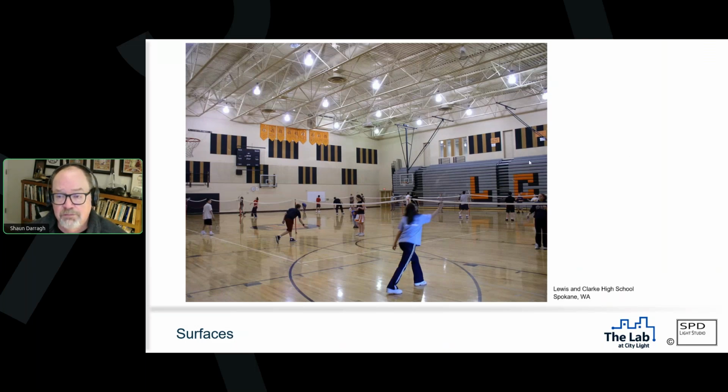where they came and they said, well, we need better lighting. We need more lighting because it's too dark in here. The reality was, if you took a light meter onto the floor, they had abundant light. But from a perception standpoint, the walls and the ceiling are painted. It's a little bit hard to tell, but you can see this fellow's t-shirt is white. This is a dark cream color. They chose intentionally to paint the walls and the ceilings this dark cream color because those are the dominant surfaces, the walls and the ceiling in this particular case.